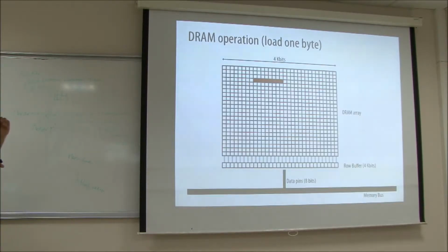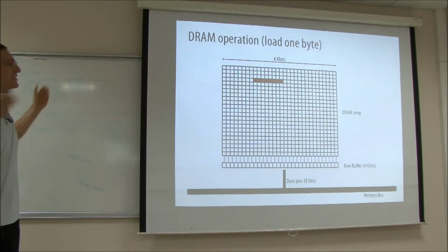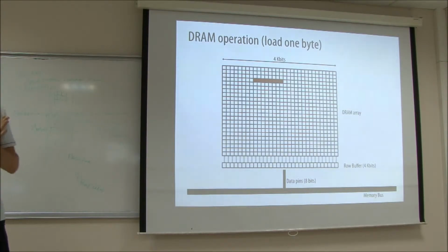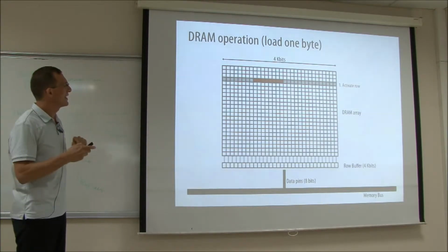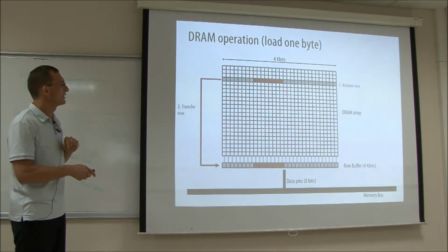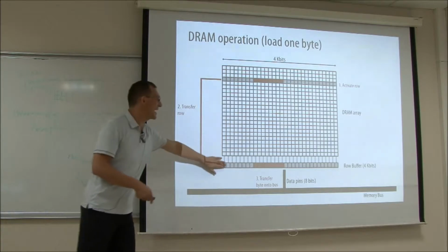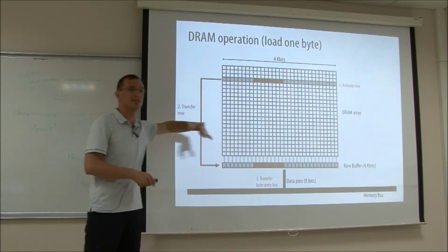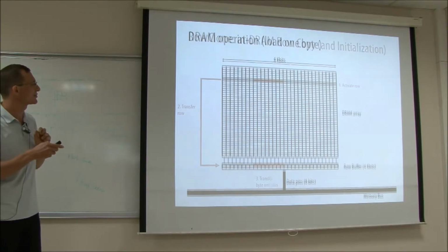I've already given you the basic idea, actually. If you look at the DRAM operation, if you load 1 byte, you cannot actually operate DRAM in 1 byte granularity anywhere. So you need to activate this entire row. And that entire row activation brings the data into the row buffer, and you just mux out the data. So we're going to exploit this fact. And the mechanism is going to be very similar to the inter-segment migration that I've introduced earlier.